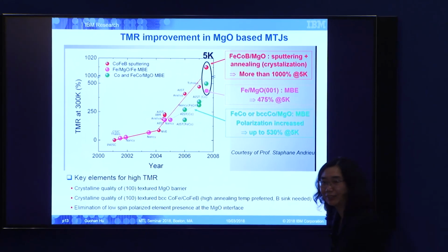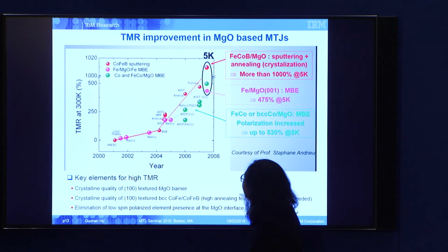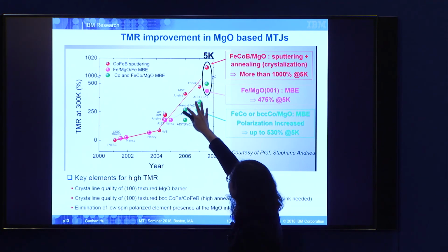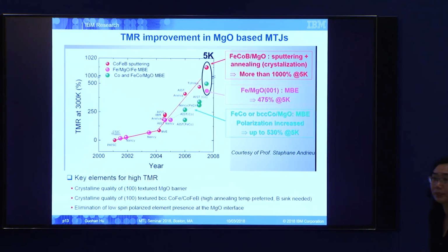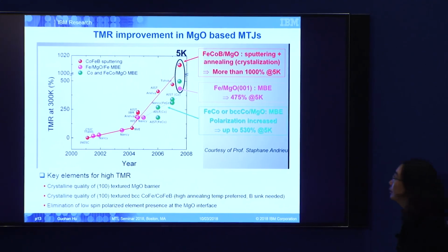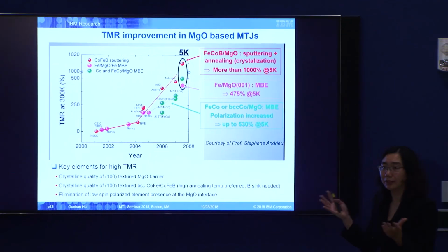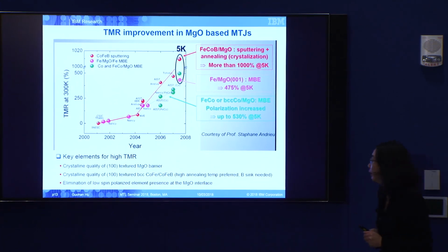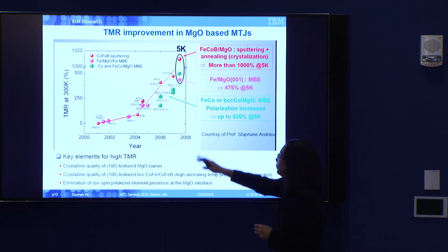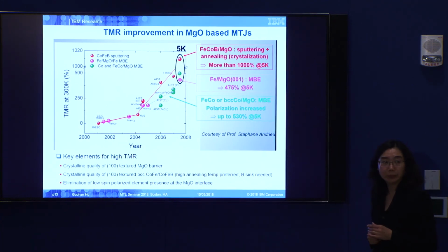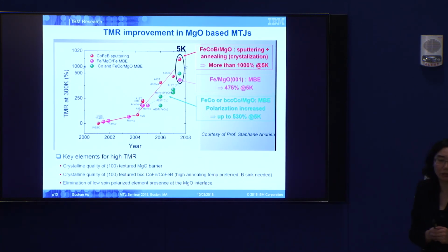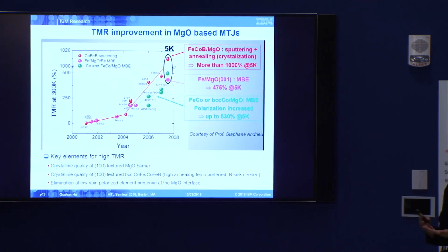So since then, there is really a competition on how high you can push the TMR, which is what we often see in the field. Over a couple of years, people were able to push it to about 500 and 600% at room temperature. I think the record is about 600% at room temperature. And then we said, OK, that's really enough for this application. Nowadays, for scientific papers, they have all sorts of tricks to make the number as high as possible. But for industry, in terms of application, people use 100 to 200% with a similar structure.